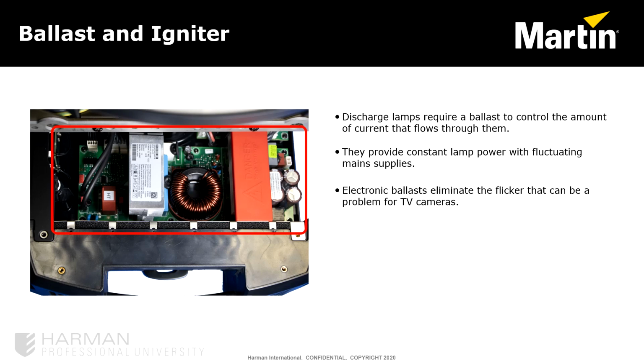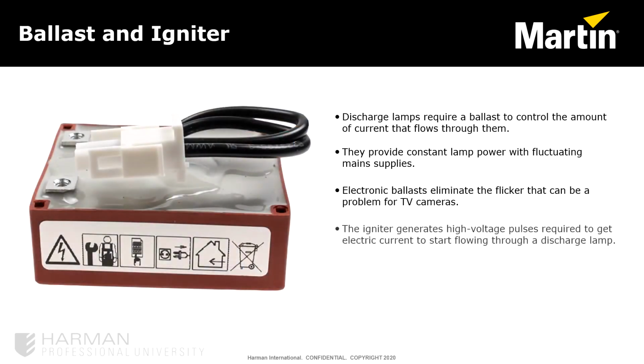The igniter generates a lot of volts, especially on the initial strike, so in testing it is not recommended to take measurements from the output of the igniter, as the input is adequate. If 240 volts are put to the igniter and nothing is happening, usually the best course of action is to try swapping out the igniter.